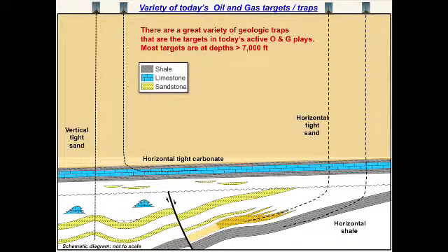Later on, we married additional technology, our ability to precisely drill and steer the drill bit over long distances, first directionally and then horizontally. This was technology that was developed in the offshore in the Gulf of Mexico and other places around the world, the UK, North Sea, etc. But by marrying directional drilling, horizontal drilling, and multi-stage fracture stimulation, we were suddenly able to attack not only vertical wells and stack sands, but also horizontally target reservoirs that were poorly productive or uneconomic without fracture stimulation.